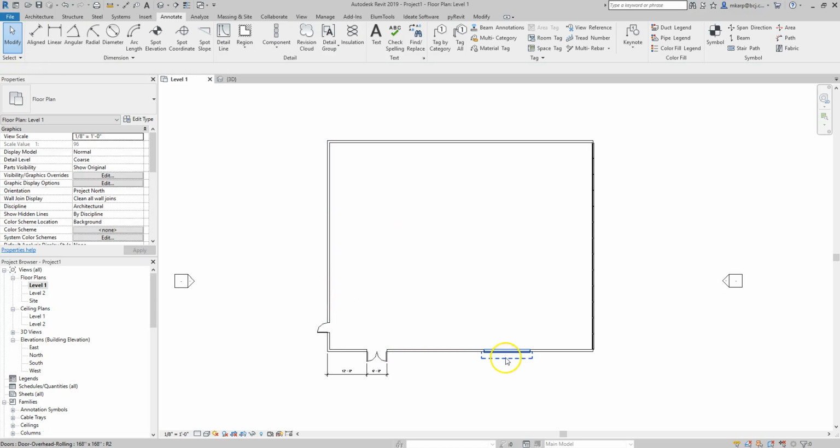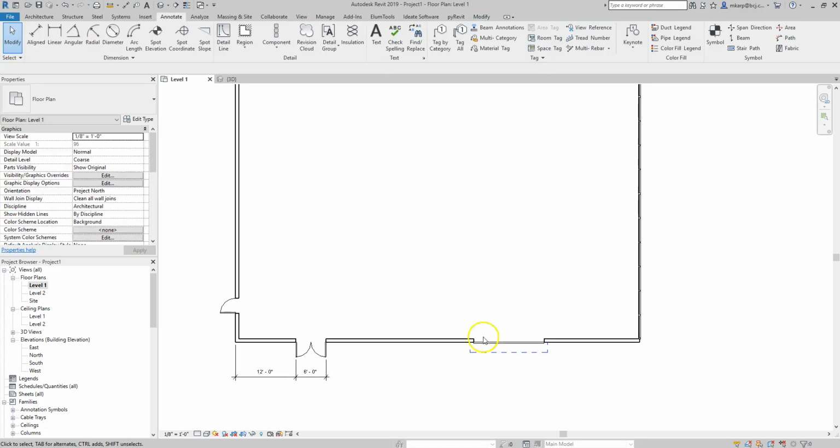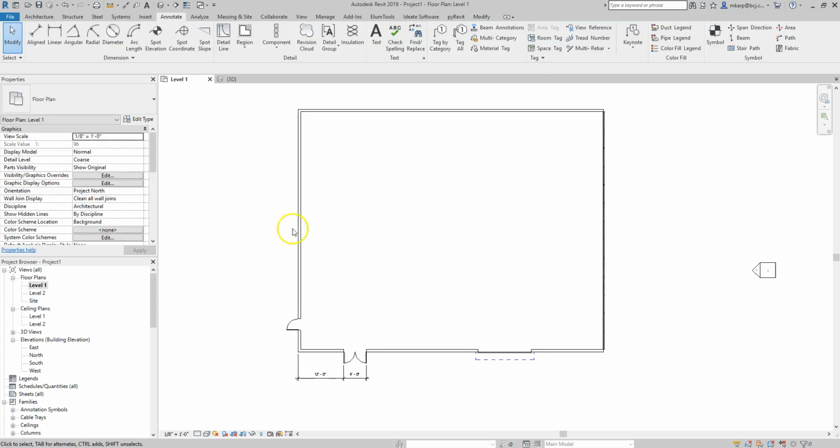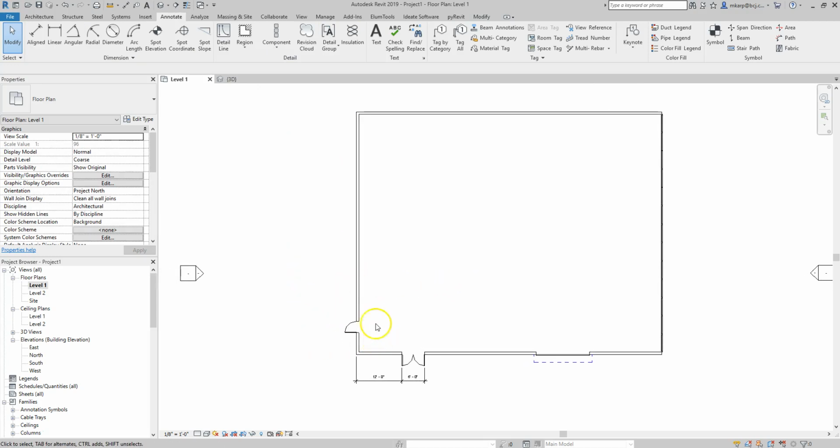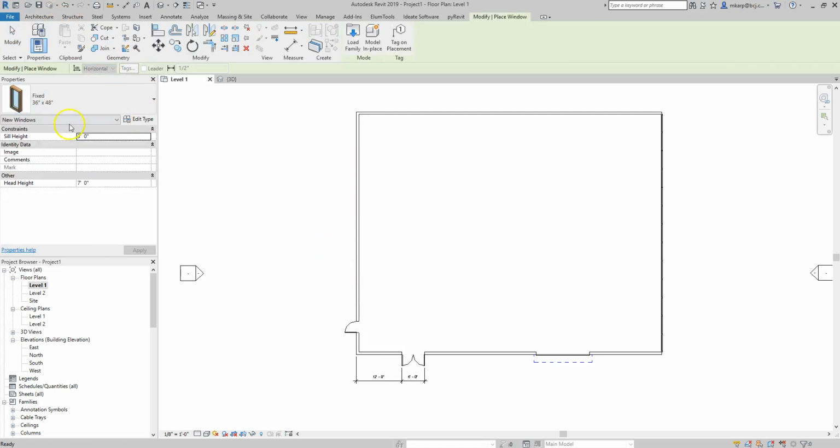Now we've gone through this. We can see how doors go in. Let's talk about placing some windows in one of these walls and what that means. And with the windows, we'll also look at changing some window types so that we can change their size and how they are placed. So with windows, we can go to the Architecture tab. There is a Windows button.